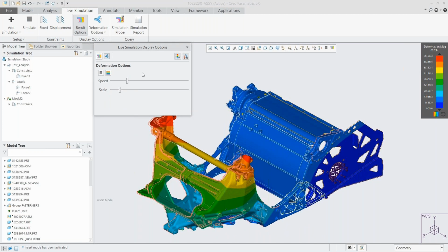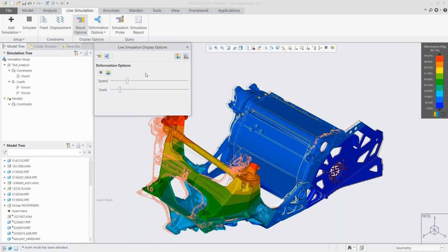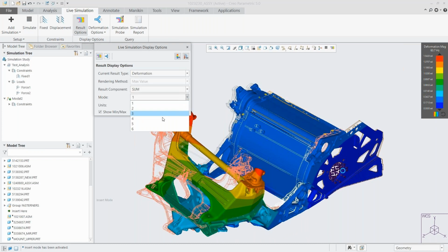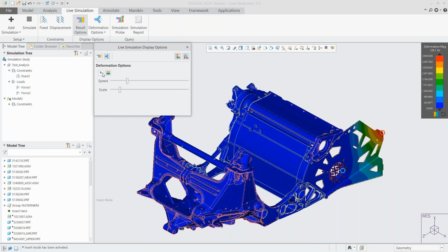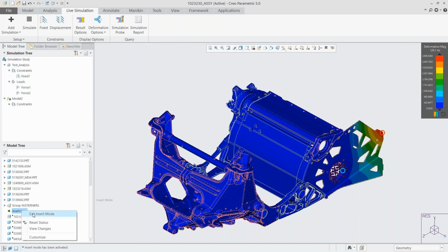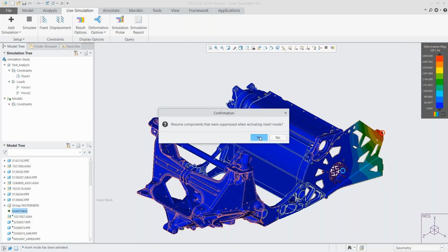That's how it's going to deform if I'm running at 60 hertz. Maybe I know it's going to be in another area as well, so I want to change that mode. I can go through and use our prescribed mode sets and see this is at about 130 hertz, and it's going to change what it's updating on the model itself. So again, let's increase the values of our study and see how this modal analysis can keep up with that as well.